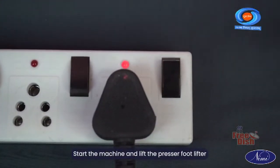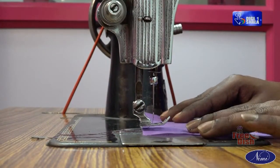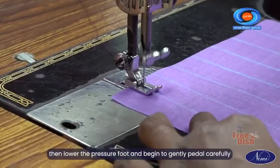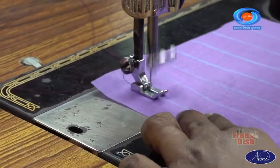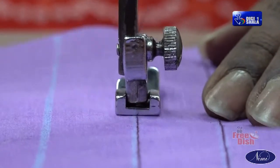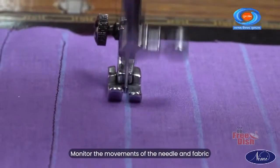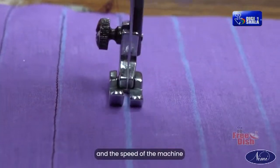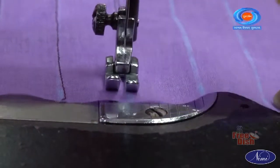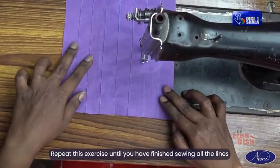Start the machine, lift the presser foot lifter and place the fabric under it. Place both hands on the fabric. Then lower the presser foot and begin to gently pedal carefully. Monitor the movements of the needle and fabric and the speed of the machine. Repeat this exercise until you have finished sewing all the lines.